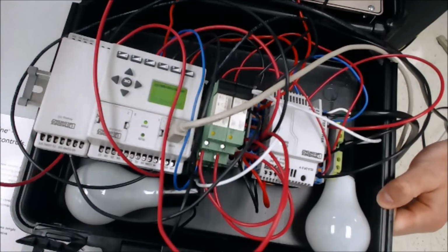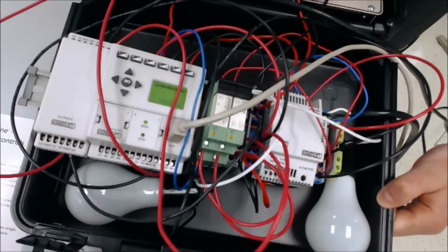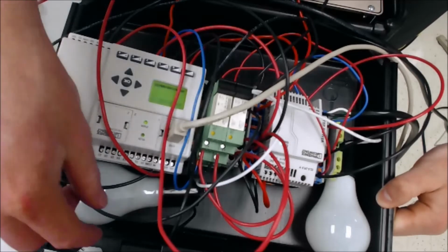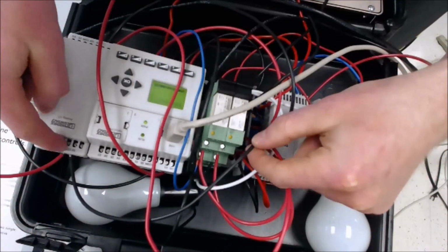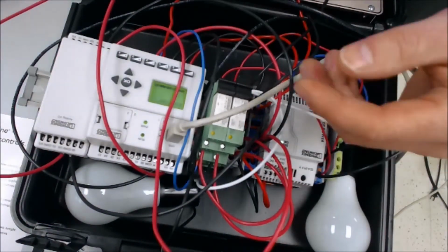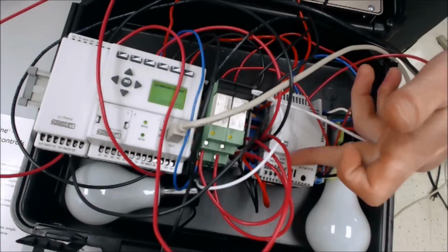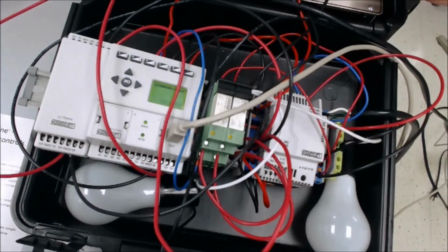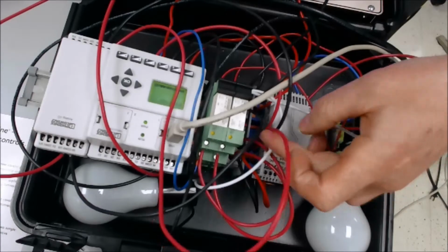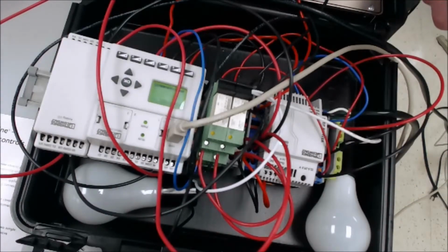So this wire and this wire right here are the analog inputs that are coming directly from the breadboard, and right here you need to make sure that you ground these analog inputs so they have something to base their signals off of. And one other important thing is that when you are working with a PLC and you're trying to connect it to other devices, it's important to ground from the PLC rack to the breadboard or whatever other device that you're using.